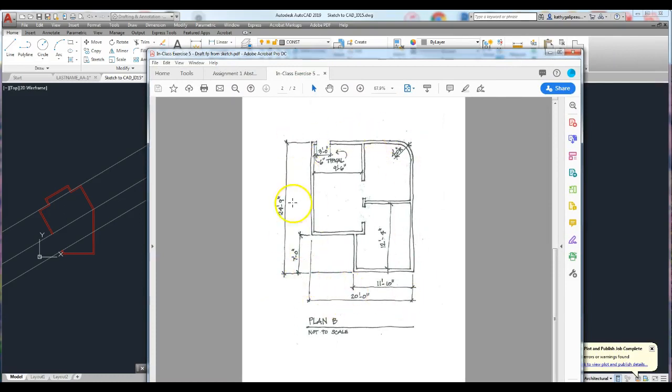It's a very rectangular plan with a little bit of a radius corner here. And so if we put construction lines where we know we have major walls, so the top, this line, and the bottom, and then the right side here, the middle, and the left side, if we put construction lines there, we can even put them for the interior walls, and it makes it so much easier to draw this plan.